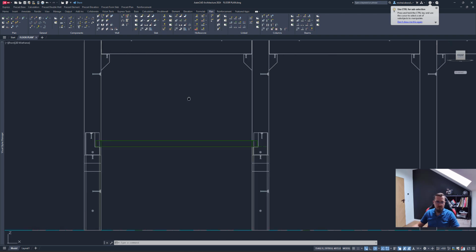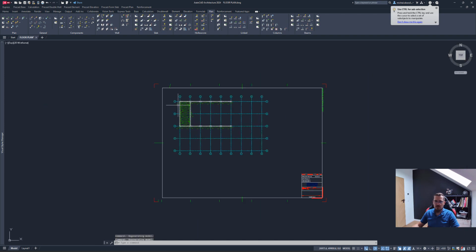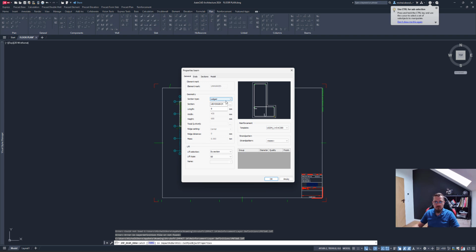And now what we'll be left with is, I just want to place a couple of pre-stressed columns, as we also have those. Those I want to be tapered columns, and those will be this type. Of course, for this particular element, I don't have reinforcement predefined. I could define that, again, going to the definition of the beams and preparing proper shapes to have that reinforcement in this. For now, I'm just going to use it as just a pre-stressed beam.